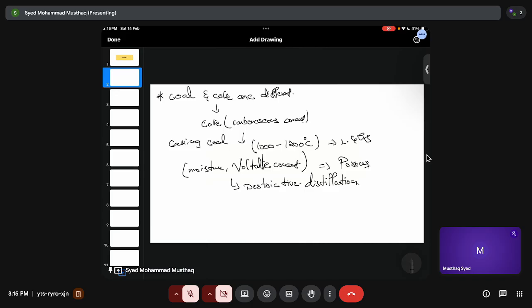Right, so moving on. Now how does this happen? We have cylindrical retorts, you can call them, or cylindrical chambers, rectangular chambers. Now you heat it, but you cannot heat it directly, it is indirect heating, so heat travels from one end to the center. Some of the volatile things will come out, and then you will have a hard mass.